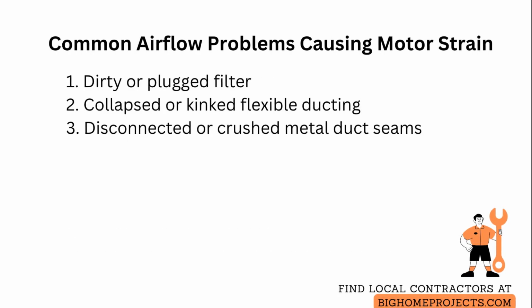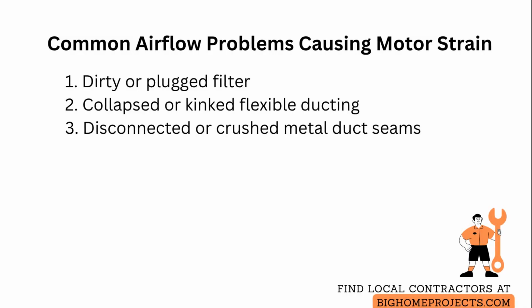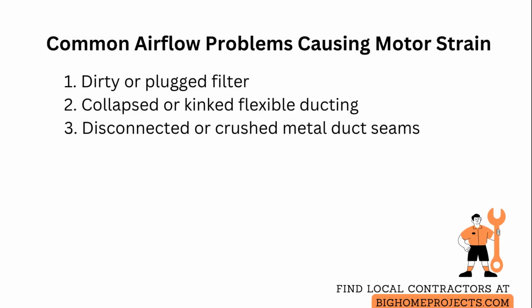The most common issue is a dirty or plugged filter, which is fixed by replacing the filter with the correct size and changing it on a regular schedule based on usage and indoor air quality.